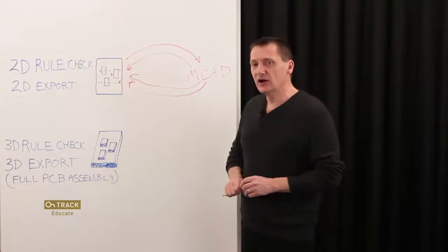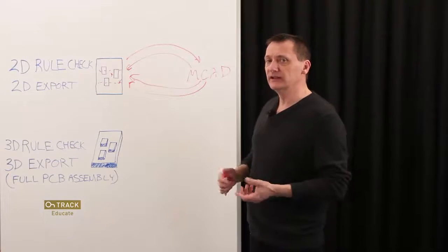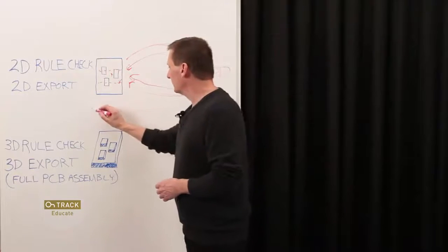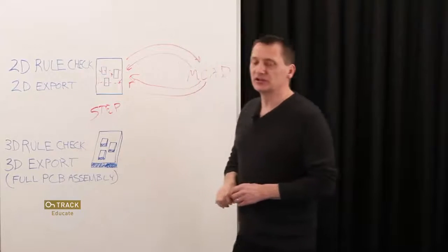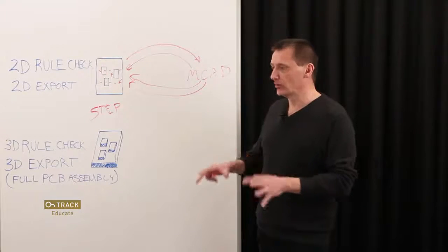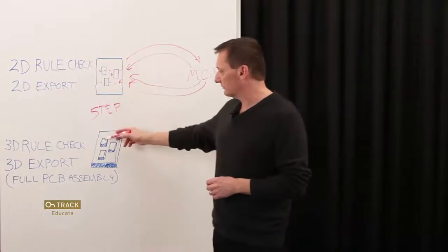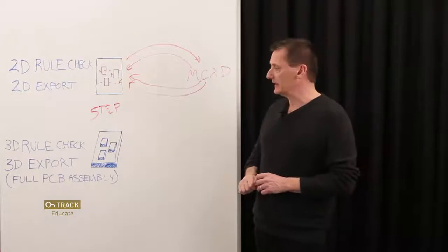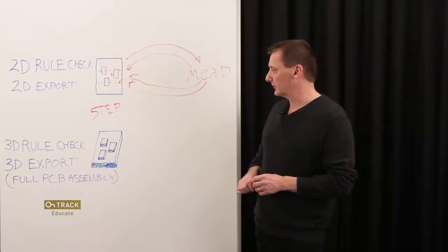By adding a common representation as a solid model, you can give 3D solid shape to your components. And that's done using a format referred to as STEP. STEP is a common interchange format that's readily available within any MCAD tool. You can work in their environment and export out a STEP model for anything as simple as a resistor and a capacitor component, or the complex enclosure. Anything that can be designed in an MCAD tool can be exported as a STEP model.